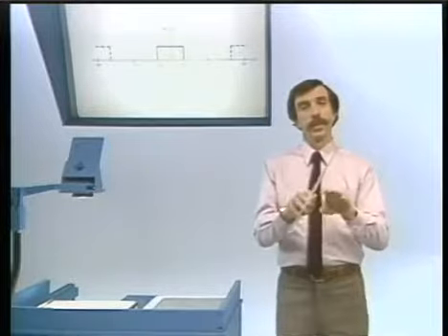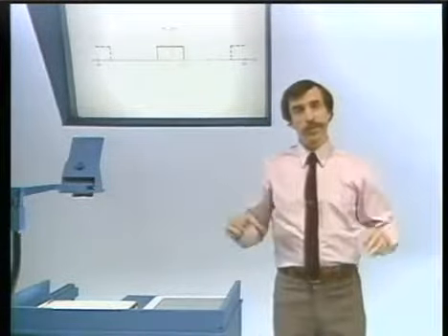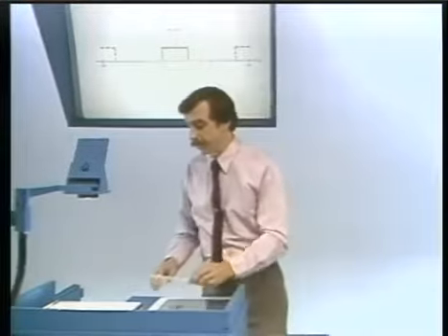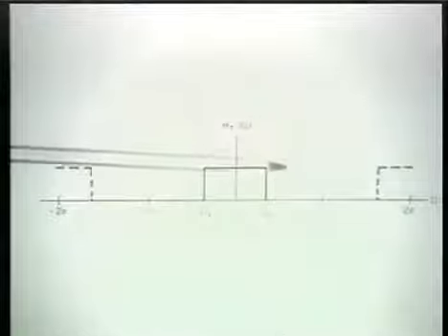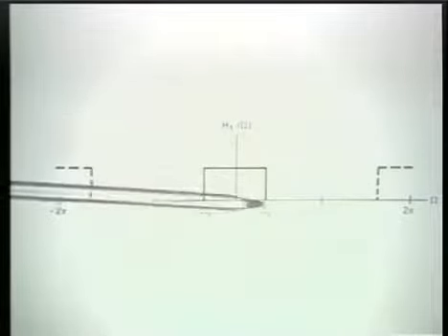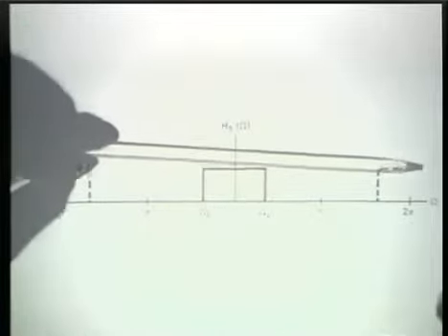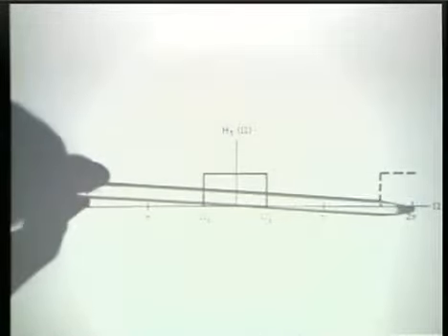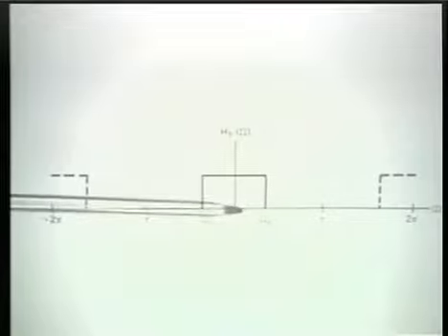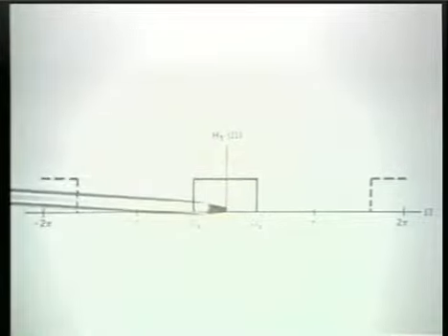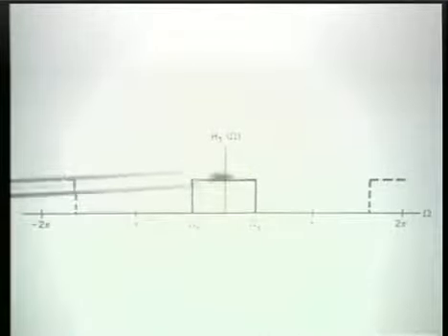So obviously, the frequency response must periodically repeat for the low-pass filter. And in fact, we see that here. If we look at the low-pass filter, then we've eliminated some frequencies, but then we pass, of course, frequencies around 2 pi and also frequencies around minus 2 pi, and for that matter, around any multiple of 2 pi.